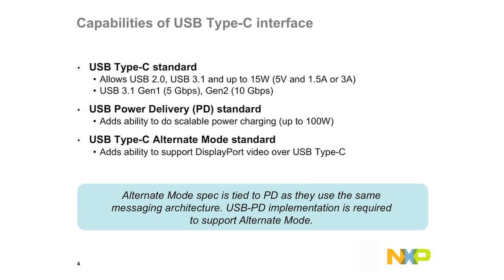So when you look at the Type-C standard, there are a couple of things I want to highlight. There are different standards written in parallel that kind of go along with each other. So to give you a quick example, when you plug something into your USB 3 port, you expect 5 volt, 900 milliamps out of it. That's the spec, right? Similarly, in the previous generation, USB 2.0, you can expect 5 volt, 500 milliamps out of it. Now, that voltage and current is fixed, right? You cannot change that. You cannot negotiate that.